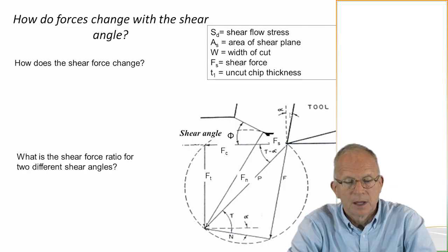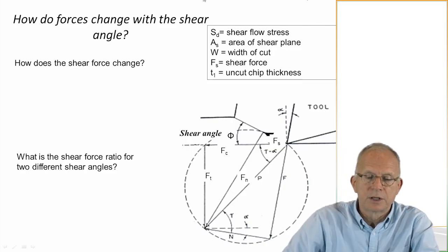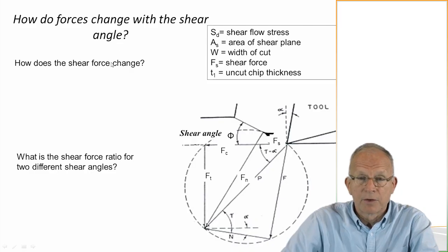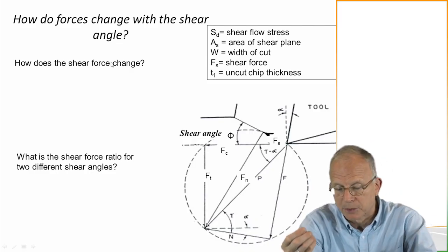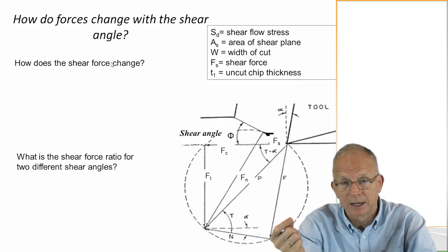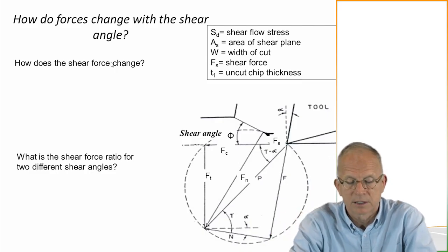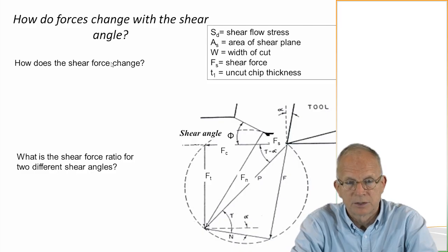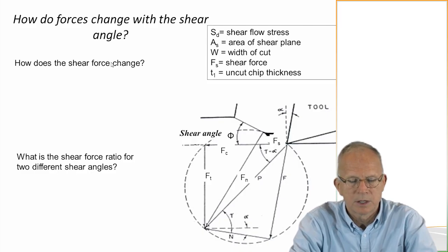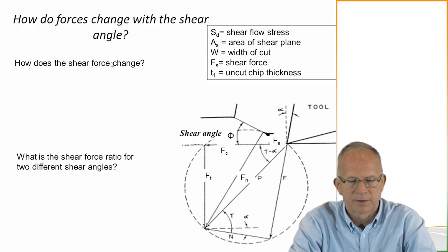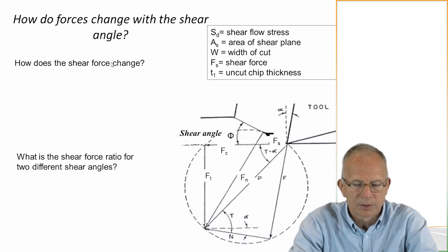Anyway, so here's a question: how can we use this? So how do forces change with the shear angle? Now, a very good machinist can pick up a chip, be careful because it's often hot and sharp, and can feel the thickness of it or mic it. You can mic it and get the thickness. Make sure it's detached from the workpiece and not moving around and not hot, and you don't cut yourself on it. But so you can measure the thickness, and you can figure out what the shear angle is.